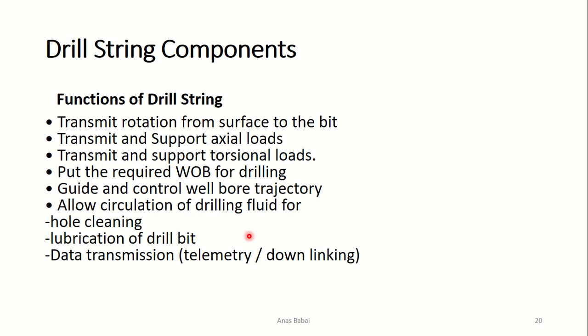Now we come to the drill string component. The function of the drill string is to transmit the rotation from the surface to the bit, transmit and support the axial load, transmit and support the torsional load, put a required weight on bit on the drilling, guide and control the well trajectory, and allow circulation of the drilling fluid.